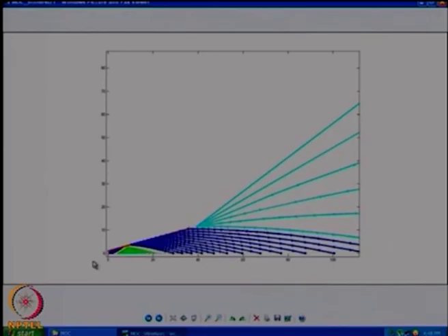And by the way, since it is a straight line nozzle, at the exit, at the topmost point, the theta is not going to be 0, but it will be whatever the wall angle is, enforced by the wall. It so happens that it starts from a 15-degree angle there, and if I go down straight it will become 0 degrees at the symmetry line. That is how the flow will be. In fact, you can still see that expanding region, just bouncing up and down across, and that is your initial expansion fan from the throat.